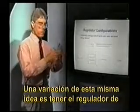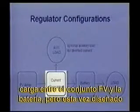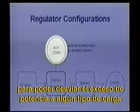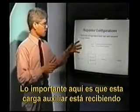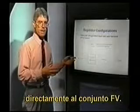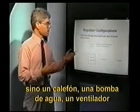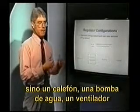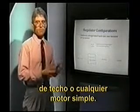Another approach or another variation of this same idea is to have your charge regulator between the photovoltaic array and the battery. But now it's designed to be able to divert excess power away from your batteries once they're full to some sort of auxiliary load. The important thing here is that this auxiliary load is getting unregulated power. It's directly connected to the PV array. So it can't be any sort of electronic device, but typically this might be some sort of heater, maybe a water heater. It might be a water pump for pumping water up into a tank. It might be a ceiling fan or other type of simple motor.